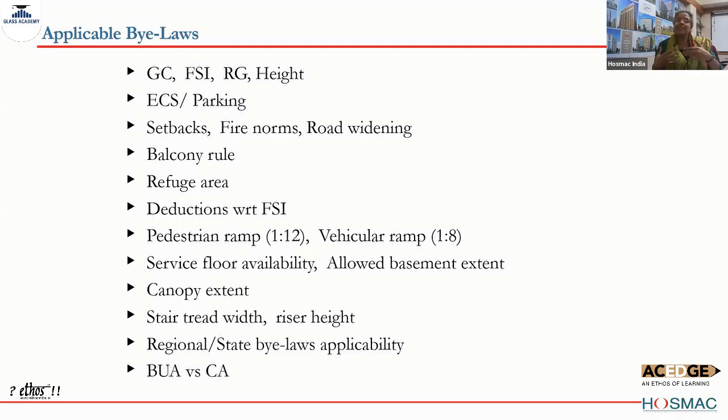That is why it's called a service. It's only service oriented. You cannot bring a human over here. So the downtakes of the plumbing are routed out from the service floor to other ducts, which take the sewage out into either, actually, the STP is mandatory, the sewage treatment plant room, or else in government hospitals, these get drained out to a septic or a sewage treatment plant outside the hospital.